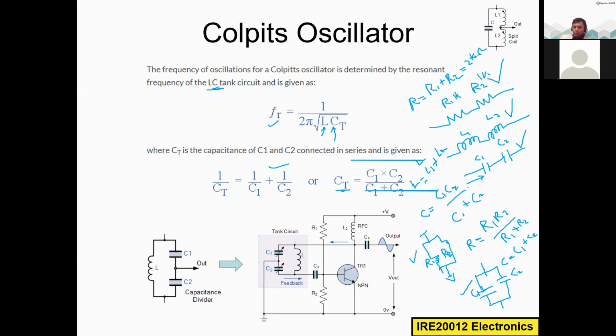Now the resistors are connected in parallel. I apply the same 1 kilo ohm and 1 kilo ohm. Then the formula is totally different, right? So what is that? 1 multiplied by 1 divided by 1 plus 1, which is equal to 1 divided by 2. So it is 0.5. The effective resistance value is 0.5 kilo ohm.